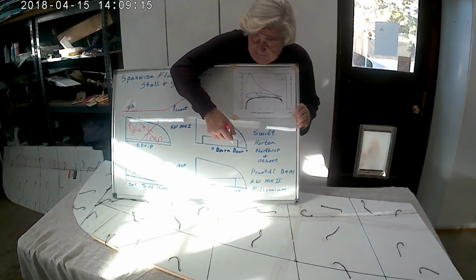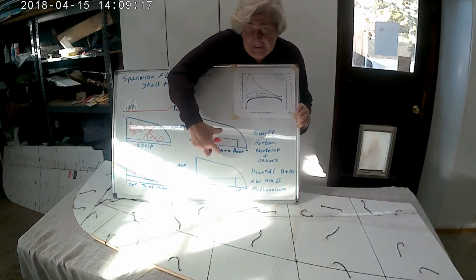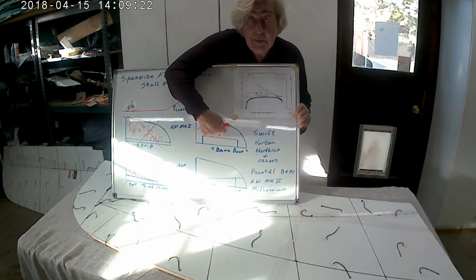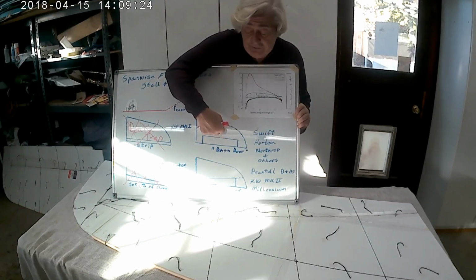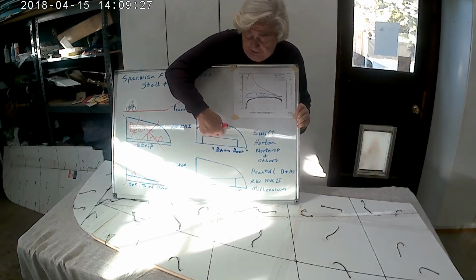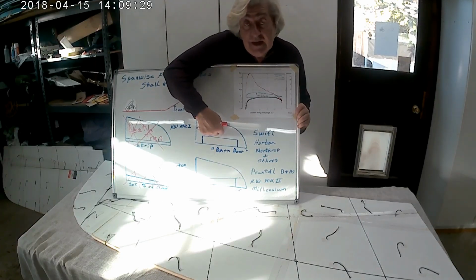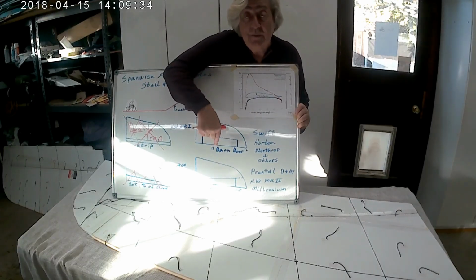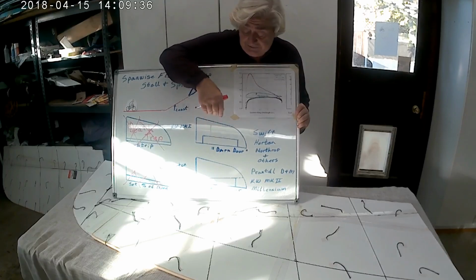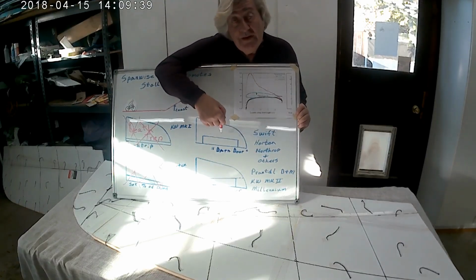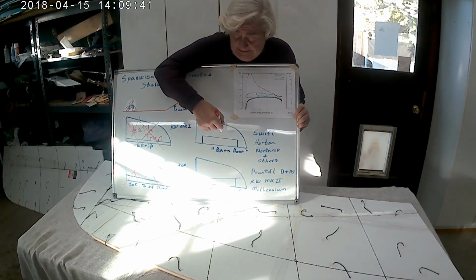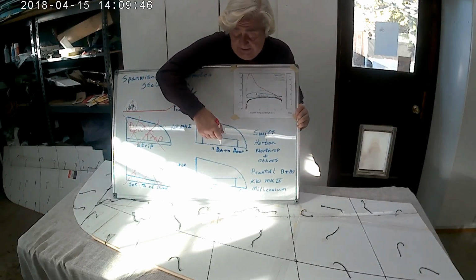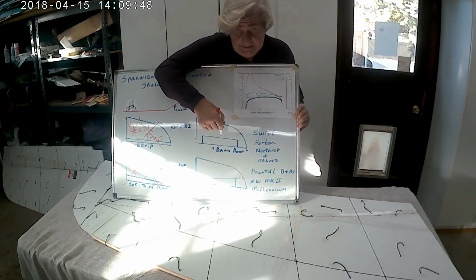You have to have this thing have a large enough chord this way so you're up into the area of maximum flow velocity or higher flow velocity. You have to get up here at some point where the air still has enough momentum in it to get up over the control surface at its maximum deflection, or around the corner and down the control surface. Where is that point? Can we do a calculation that says, oh, I have enough momentum in my flow to get up this hill when it's deflected at 30 degrees?